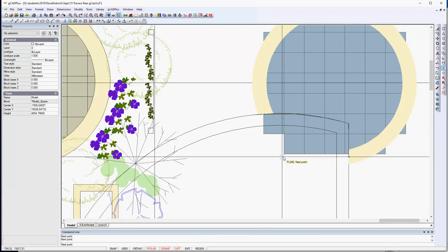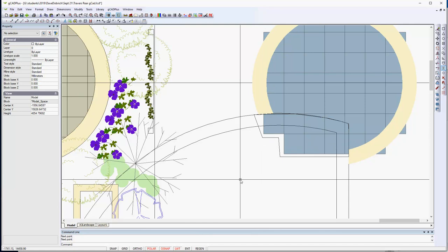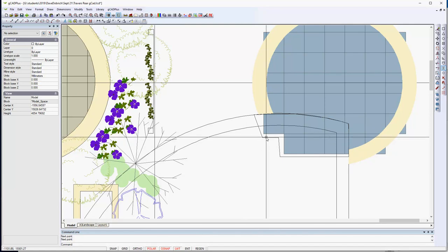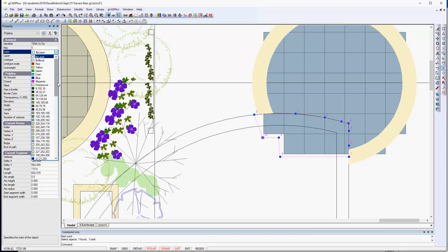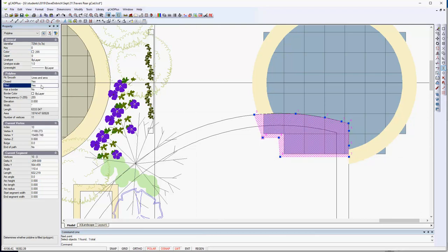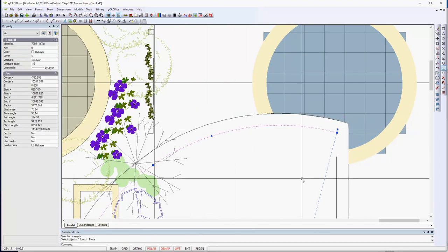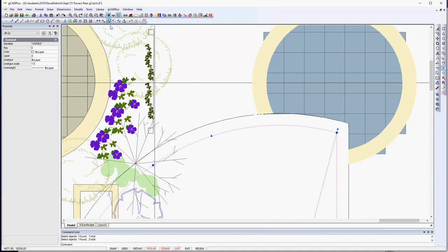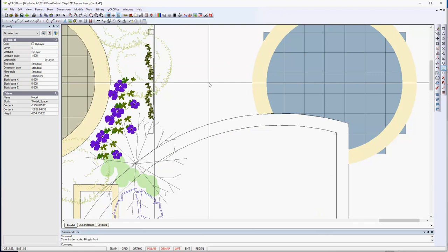I'll stop about there, come over here, there, and to here, and then close it. We can then select that new polyline, apply white on white, which will make it opaque, put a fill on, and unselect all. We've done reasonably well, but I think we just need to bring these two lines here using tools and draw order and bring them to the front.